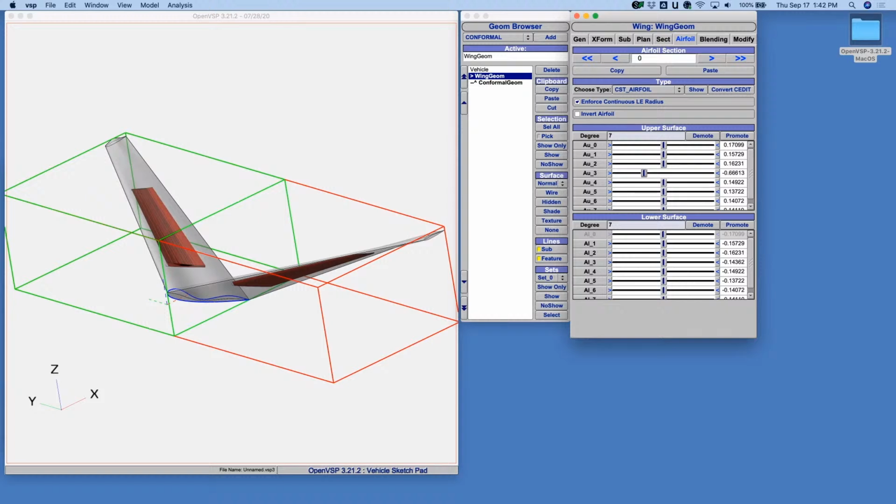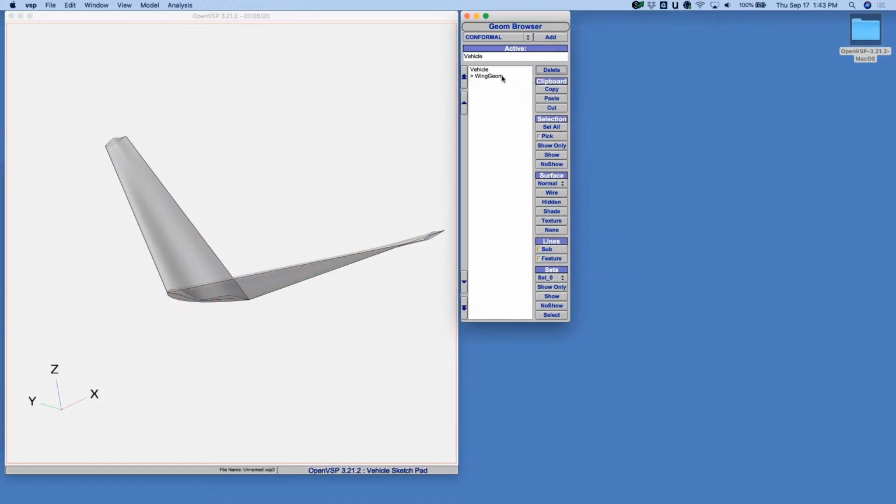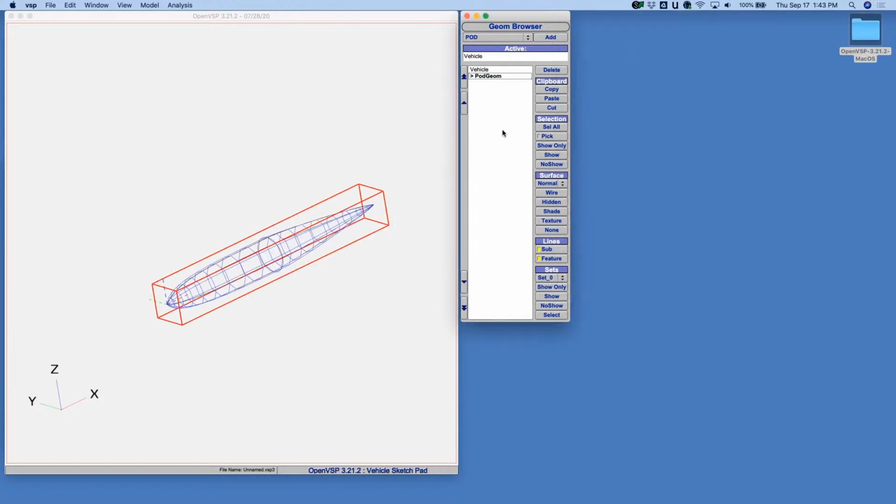And if I could add on to that as well, sometimes it's hard to really back out exactly what the foil is, and maybe even a CST might be a bit too far in the other direction. If you're trying to just get it to where it approximates whatever the airfoil looks like, you can usually get that by picking either a NACA 4 series or a 6 series, whatever flavor you like, and just letting it float through some of those parameters. So if you find one that's in a class of airfoil that is pretty darn close, you can play with far fewer parameters and get something really close to what you need.